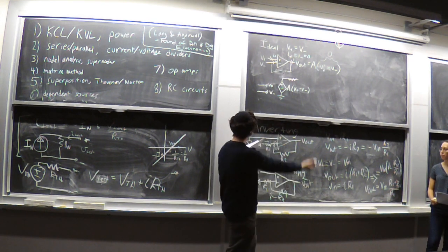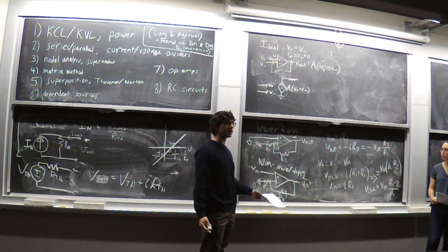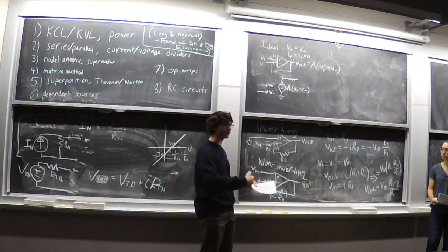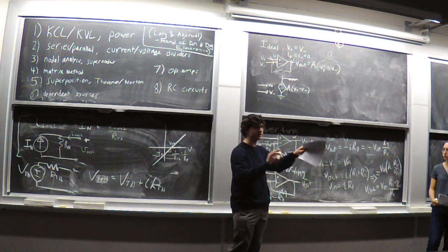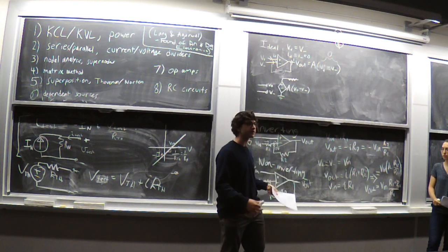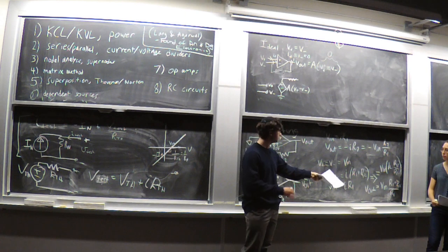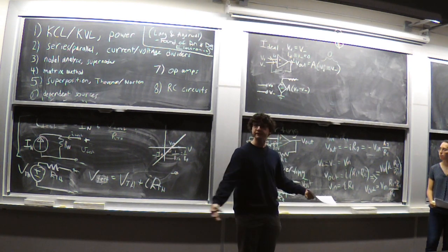You'd just be solving it like any other circuit with a dependent source in it. What you'll often see is that at the end of your analysis you make some nice assumptions, such as A is close to infinite, and this resistance is very small, and you simplify to the nice values you would get had you assumed the op-amp was ideal in the first place.